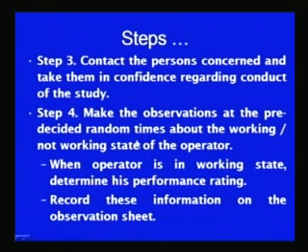The randomized timetable is obtained with the help of random tables, and those will be part of the plan which will be developed for carrying out the work sampling study through random observations of the shop floor. And when the operator is in working state, the operator's working performance is assessed, the performance rating is determined if the worker is being observed, and then the same thing is recorded in the observation sheet.